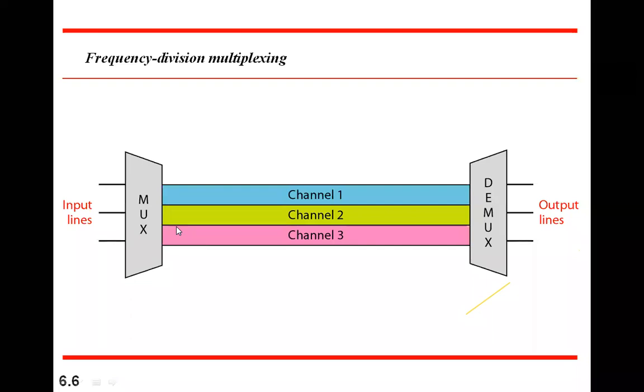But one more disadvantage is also there. When there are too many panels like this, and if these filters are not perfect, they can also generate one more thing called intermodulation products, which can get into other parts of the spectrum. That also we have to provide for. All these things are some merits and demerits of this. So keeping in view all these things, we have to utilize frequency multiplexing and design the system appropriately.